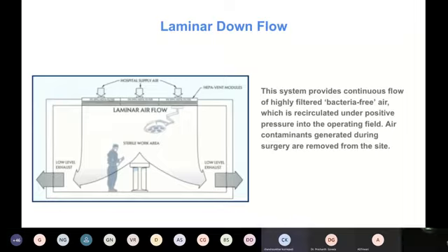And when laminar flow stations provide 90 to 120 FPM of velocity, through the risers, whatever we install. Generally, what happens is we go with 4 corner risers in the operation theaters. So the airflow pattern is with the highest velocities at the bottom. So turbulence is created on the top, where the air is not going to be laminar. This is not observed in most of the hospitals.